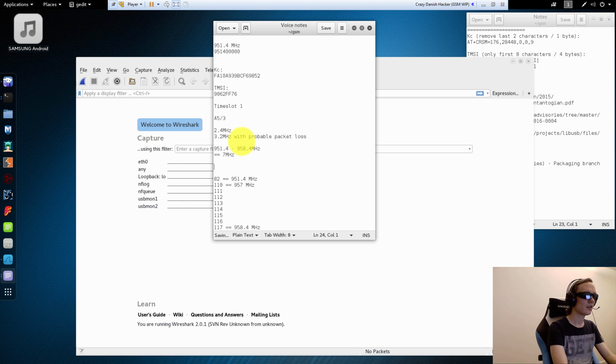So even if we had a lot of space, you can see we only have one RTL-SDR, and even if we're maxing it out, we won't be able to listen, because we are listening both ways. So if we're listening on, for example, 950, and let's say we are listening with 3.0 megahertz, then for a wideband capture file, we are listening on 1.4 megahertz on both sides.